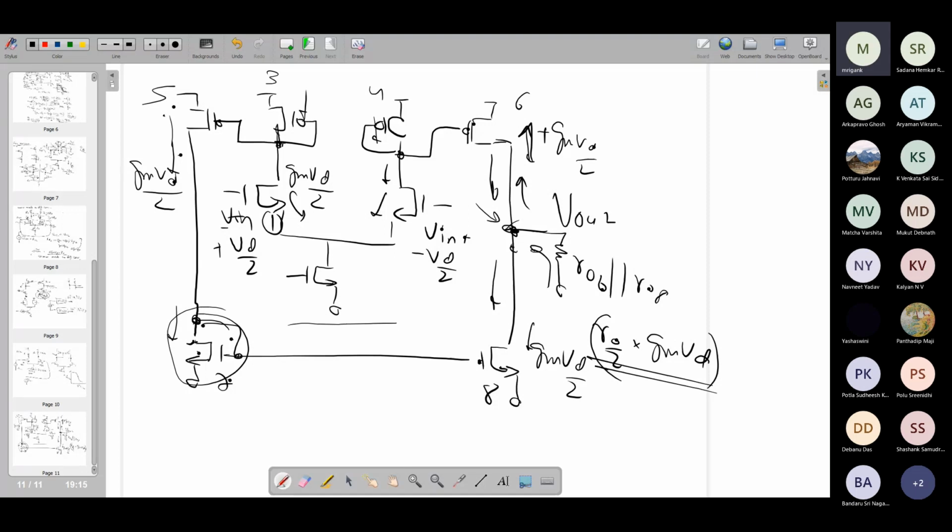So let us, here, modify certain things. Suppose I keep the input stage the same, and I add some more transistors in stack. Now, suppose I do this, right? So these are additional PMOS and one NMOS transistor, just like in the cascode amplifier. So I have just added two more transistors in cascode. Now, what is the situation? How do I find out the gain?